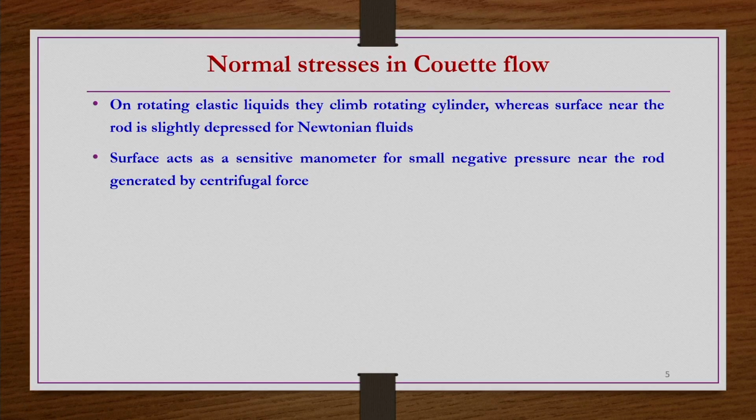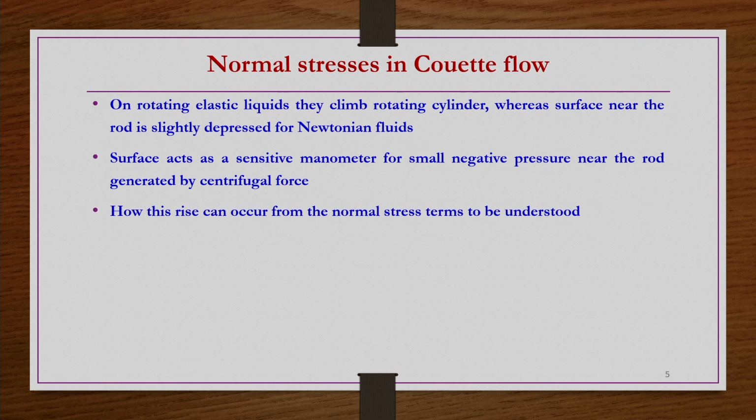The liquid surface climbing the rod acts as a sensitive manometer for the small negative pressure near the rod generated by the centrifugal force on rotating the cylinder. How this rise can occur from the normal stress terms is to be understood now.